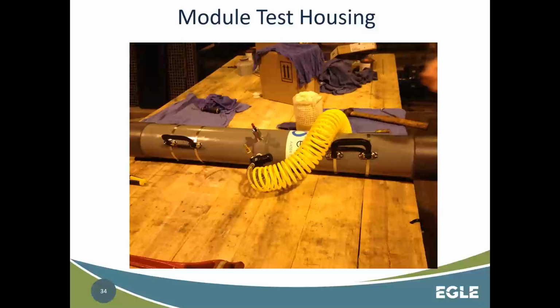that indicates that that one little fiber, and if you're my age where your eyes are starting to get bad, you're probably going to need some cheaters because they're small little holes, but you'll see air bubbles coming out. And then the manufacturers have these special little plastic pins, and it takes a little eyesight and dexterity, but you just put the pin in and then snip it off. And then you have essentially taken that one little fiber out of service.